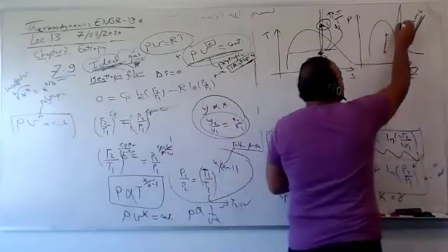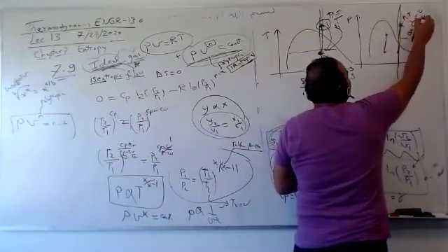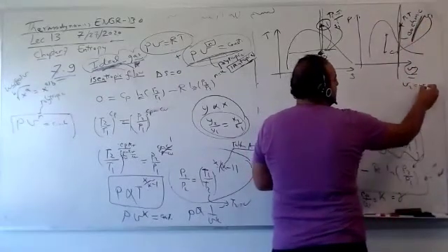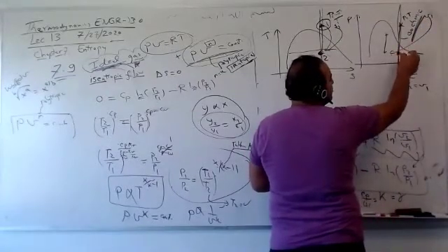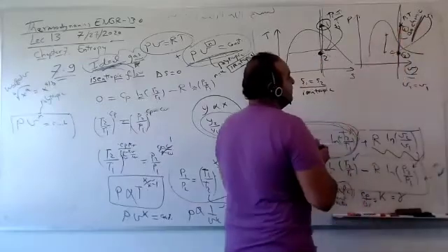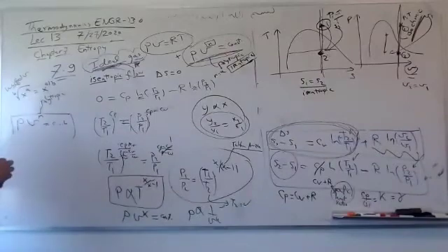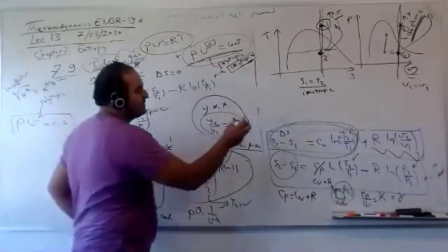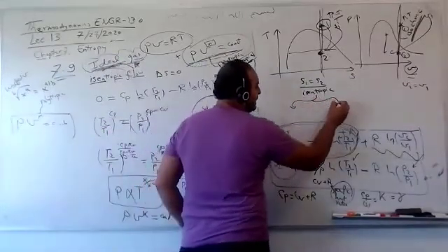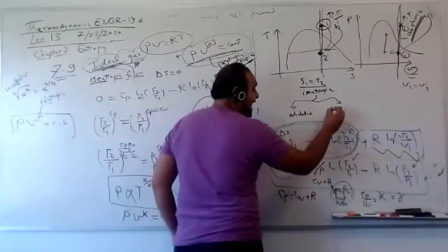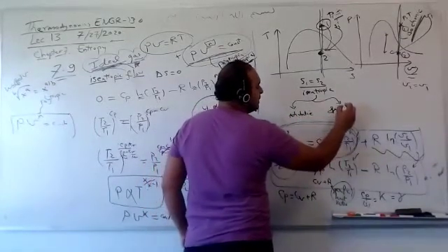If you have here, let's say P and T, you can obtain, for example, V1. Give it to V2. So you need only one piece of information at 2 because it's a rigid tank, for example. So isentropic means two things: adiabatic and reversible.